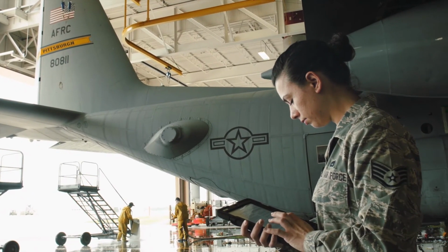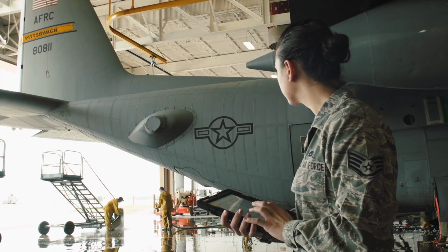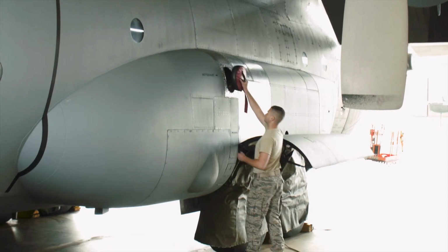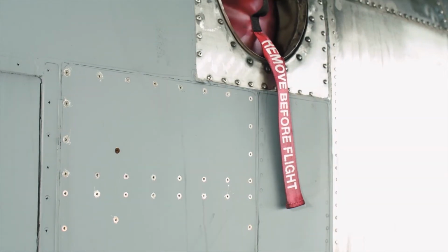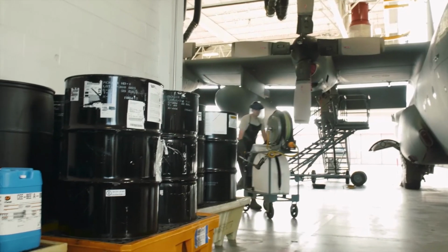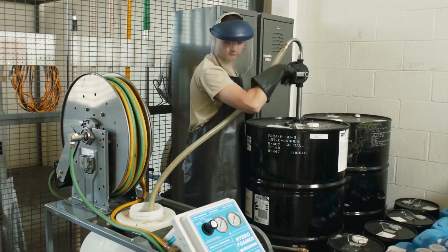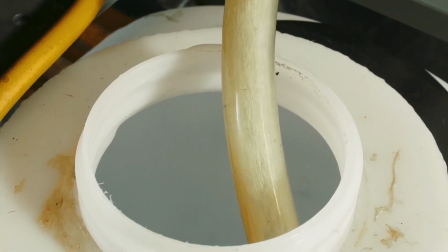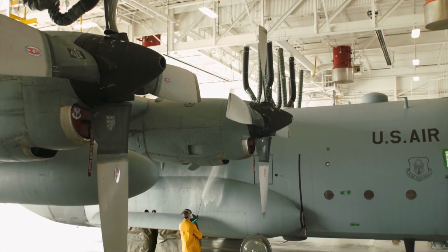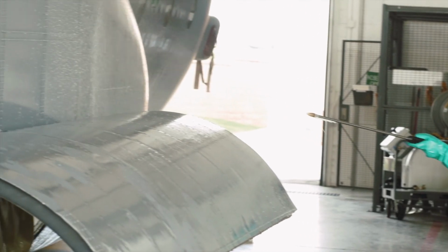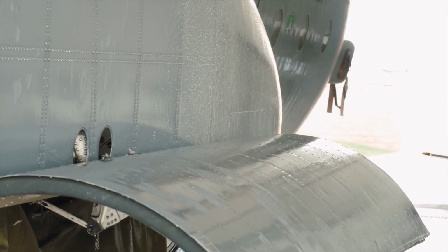Wash intervals are typically shorter in severely corrosive environments. Before starting a wash, check the applicable technical data for preparation and cleaning requirements. You must cover all areas that should not be exposed to cleaners and solvents. Be sure to use specified cleaners, and if an automatic dispenser is used, set the dispenser to the proper mixture ratio. Avoid spraying cleaners into areas containing exposed connectors or sealed bearings, or where drainage is inadequate.